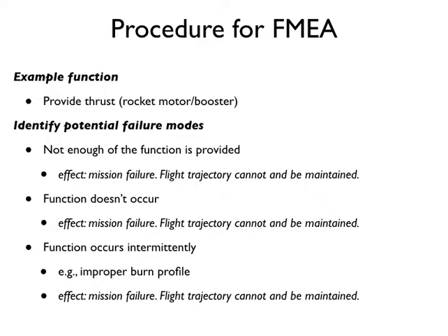Essentially this slide and the previous slide are ways to look at how the functions of the system can fail if the components are not available. But I should also say that you can apply this same sort of methodology to components. That's because all the components have functionality assigned to them, in terms of how the system is supposed to work. So even if you do know the components, you can take this methodology and apply it to the components as a way to get more failure modes of interest.